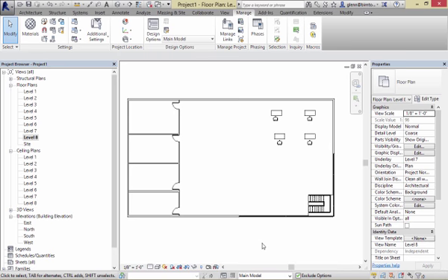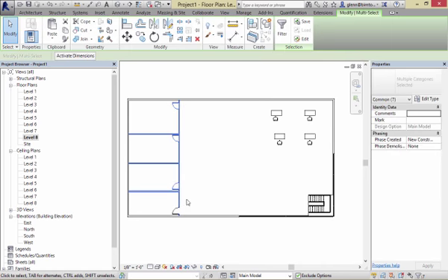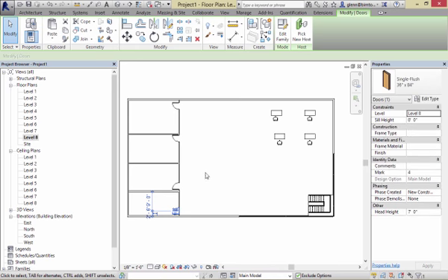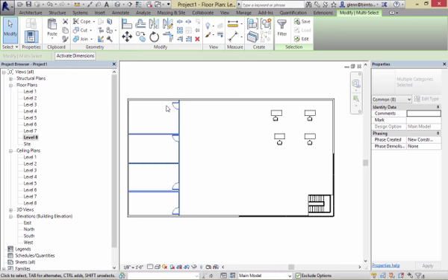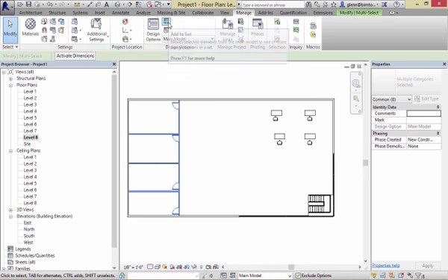All your objects are considered main. If I choose some objects, like these guys, you can get that little door too. Okay. Oops. Try that again. Okay. I can add them into an option set. What does that do? It takes them out of the main and says, okay, you're in one of the variations. You may not be in both the variations. To add them into the set, there's a button down here which adds to set. It's also under the Manage tab, right there, Add to Set.